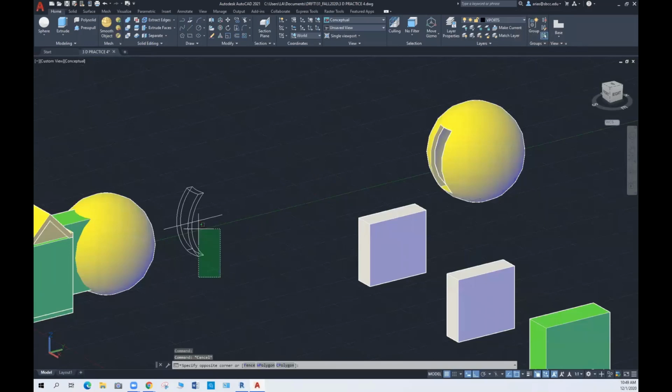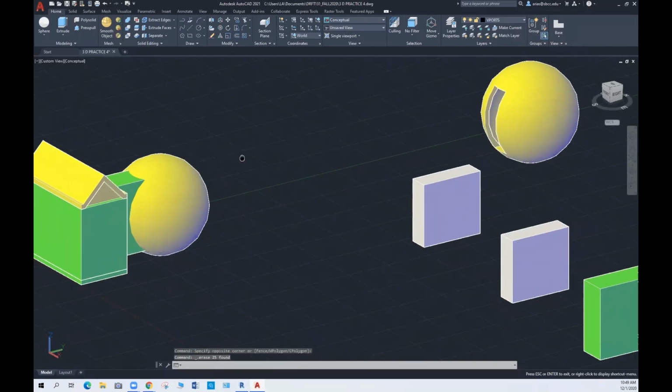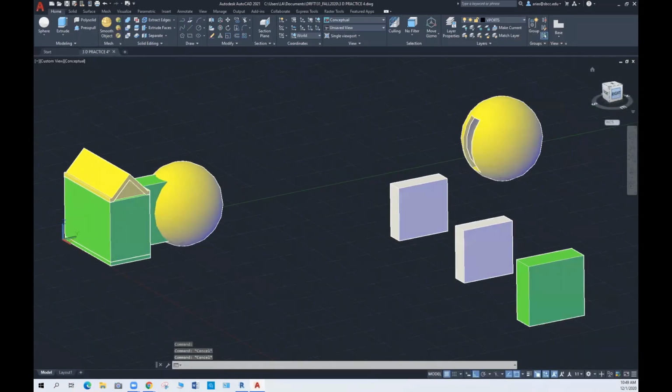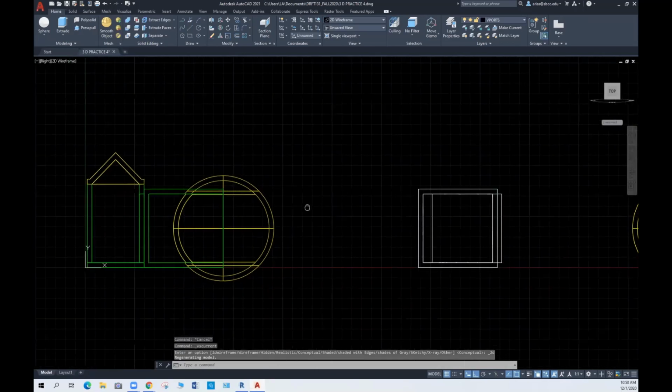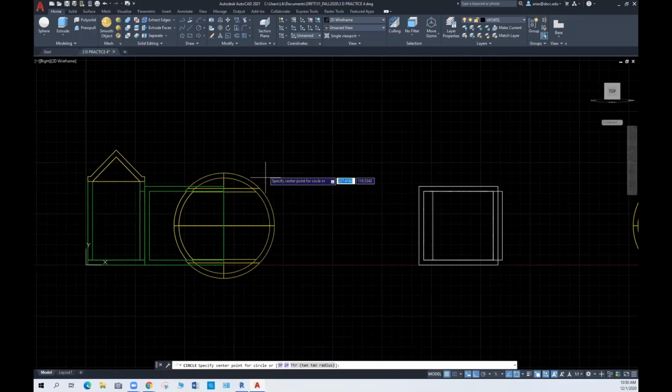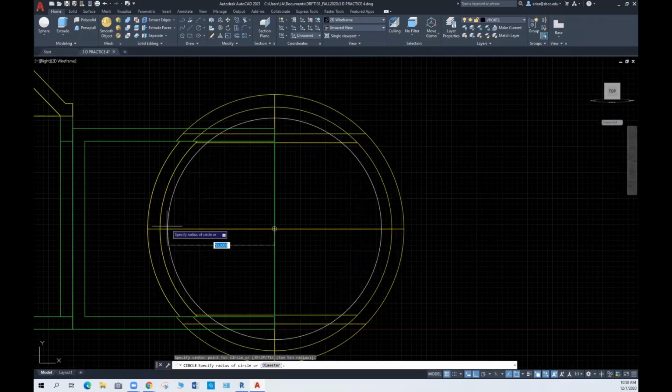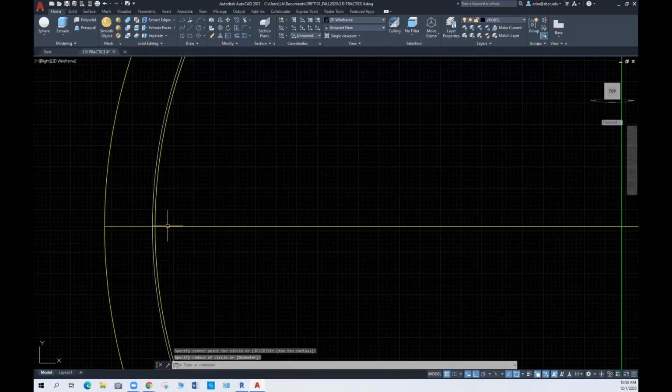All right, so all I'm wanting to do is this. So let's do a right view. UCS by view, and then we're going to do wireframe. Now I'm going to create a circle, and I'm just going to do it close to... oh, there it is.